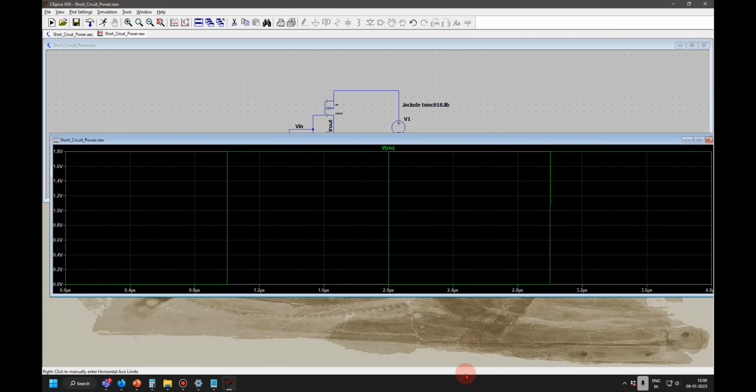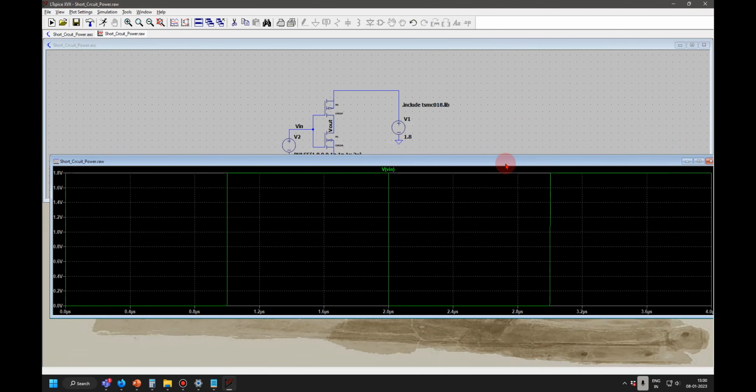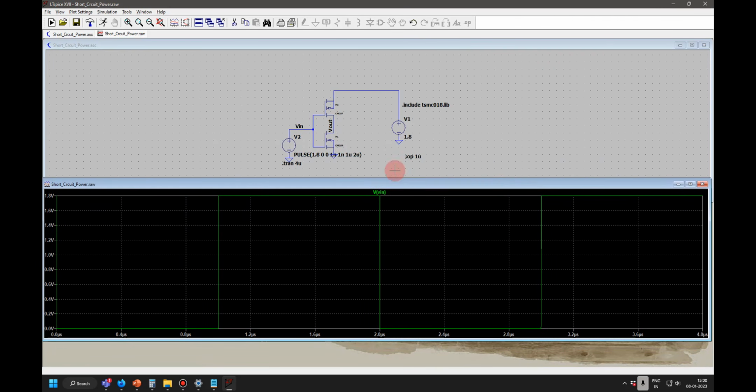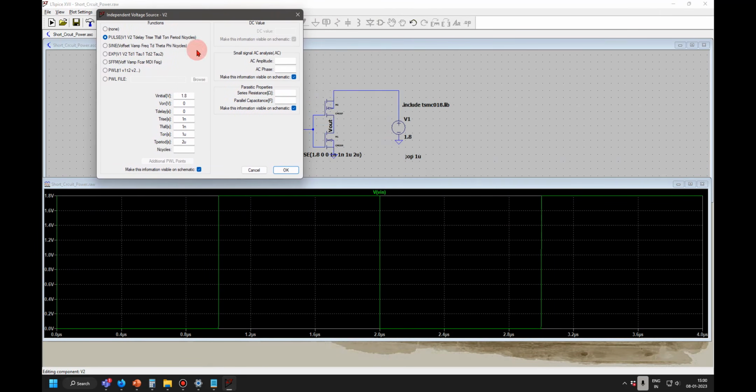Can you explain once? There is a change between initial and on, right? Yes, that I didn't get actually. You are swapping the values. Okay, see what the properties are. Let me compare. V initial is 1.8 volt, so this is taking 1.8 volt. V on is 0, it is 0 here. This is actually swapped for some reason in LTspice.